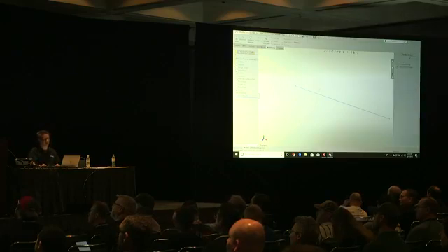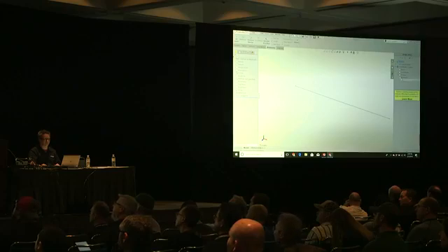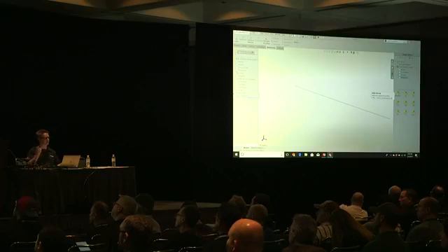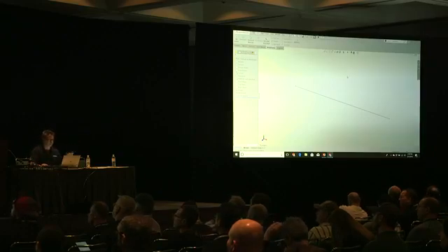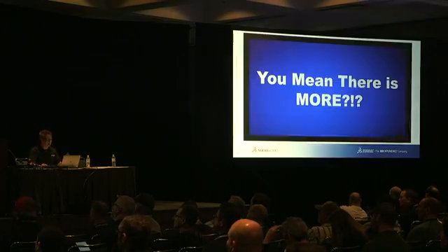You just have to come over to SolidWorks Content, Weldments, pick one you like, hold down Control, click on it, download all those files. I did nothing. I held Control and I clicked, and now I have a whole lot. There are still people that didn't know that.